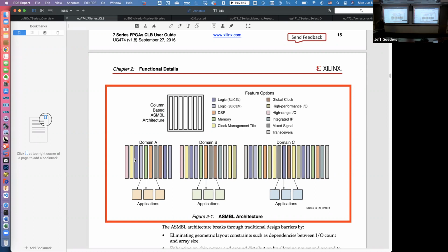And so the mental model I have is a little different than what's in your 220 book and what Dr. Goeders drew with his 2D array with horizontal and vertical routing channels. When I'm inside Vivado looking at one of these designs, my mental model is columns of logic interspersed with columns of interconnect, realizing that the interconnect jumps up and then runs sideways over the top of the logic.